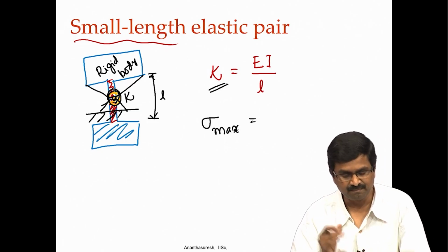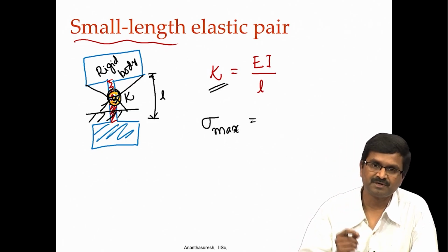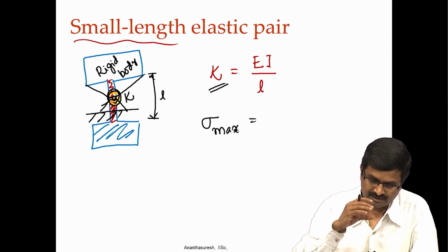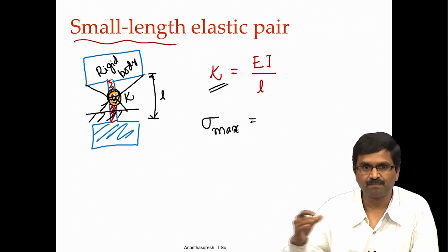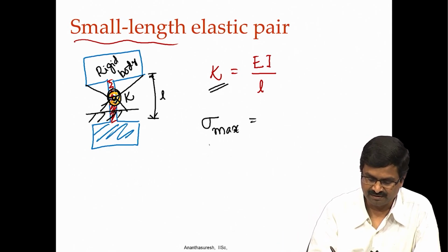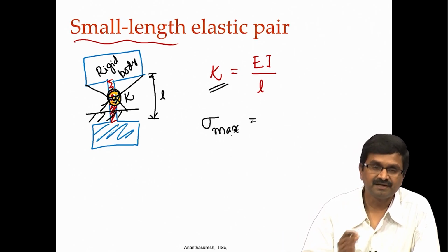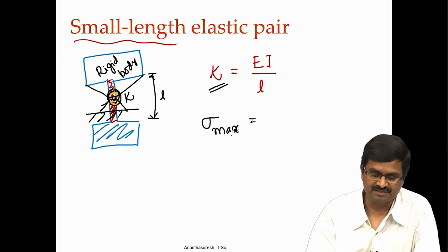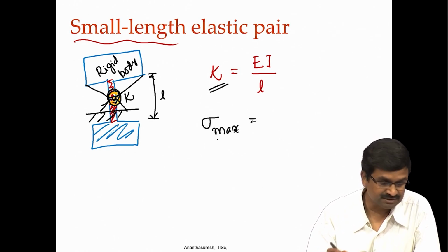When you take meshing, you have to have very small elements or take a lot of effort to use different mesh density in different portions of the mechanism. So, if you want an accurate estimate of stresses, it will take a lot of effort, but these people have not only gotten torsion spring constants, but also expressions for stress.